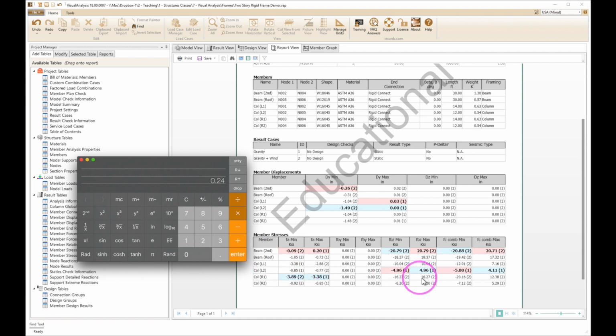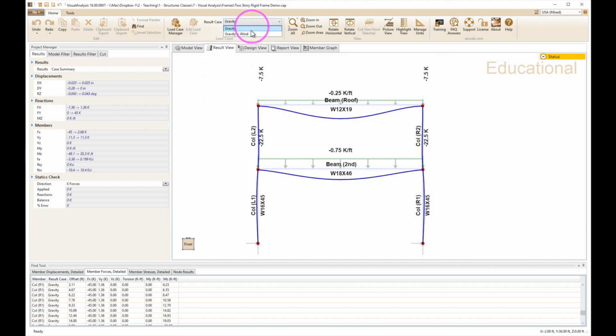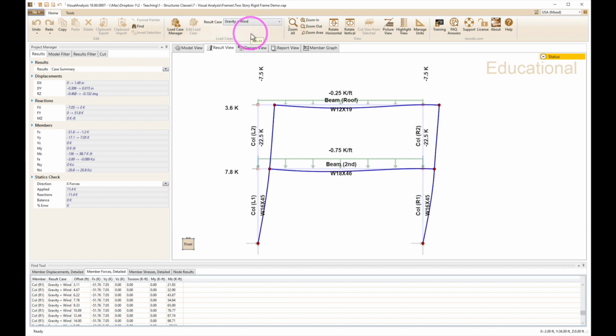Then the bending stress that is based on 22 KSI allowable. So I'll take that 16.27. Divide that by 22, so another 74% there, and then we add those together, 0.98. So I'm right on the money. So that's going to be our final selection here. And there's a loading and the final results and the deformed shape under loads.